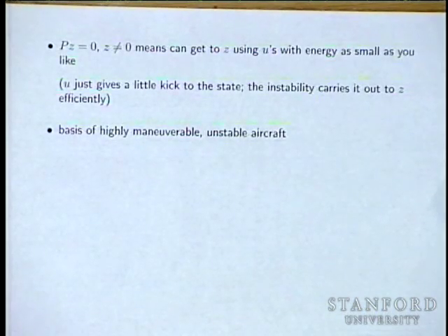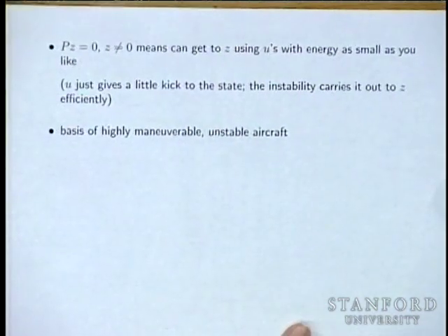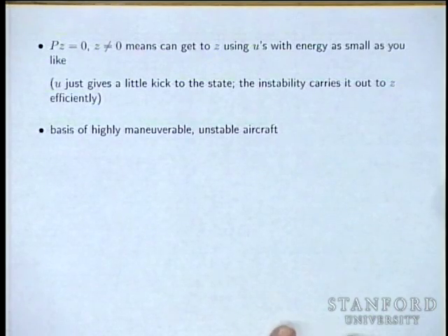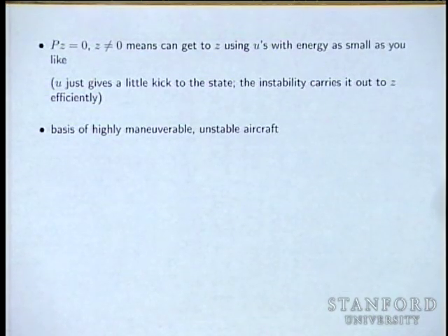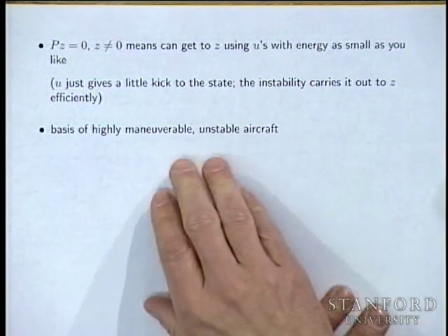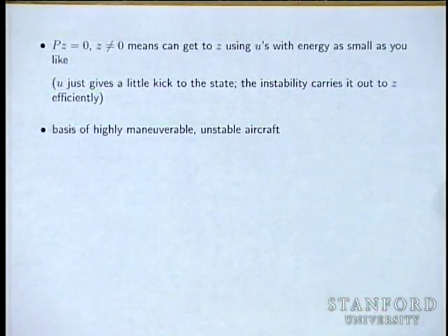Because it's open loop unstable. That's what they mean by statically unstable. Most other ones are stable. Commercial ones are, at least so far, stable. I think they're probably going to stay that way, but who knows? So with forward swept wings or statically unstable aircraft, you might ask, why would anyone build an airplane which, sitting at a trim position in some flight condition, is unstable?